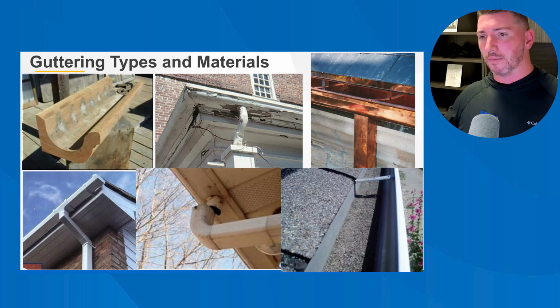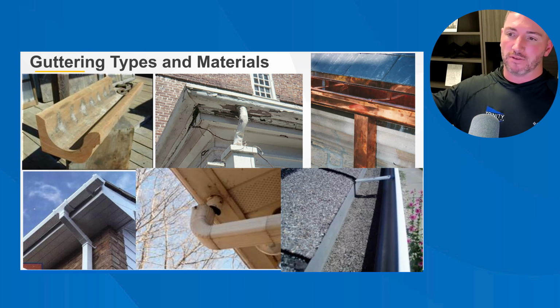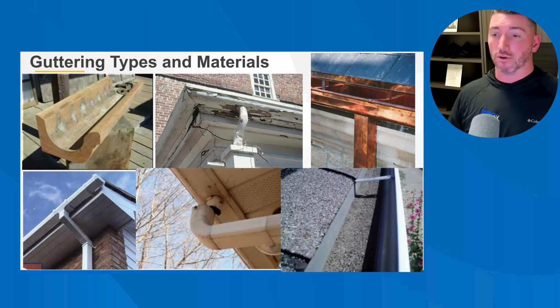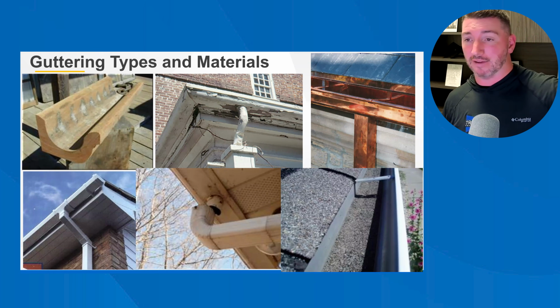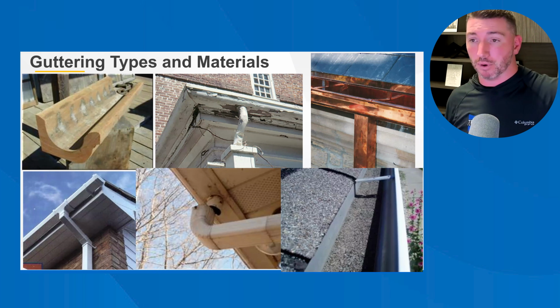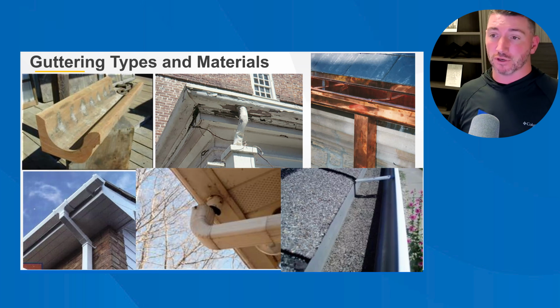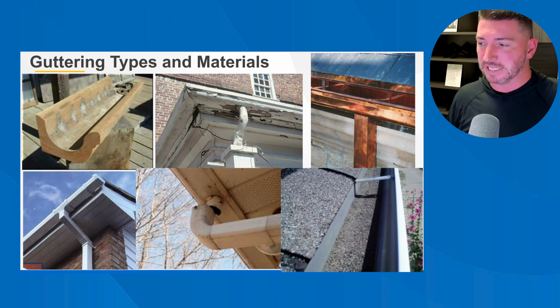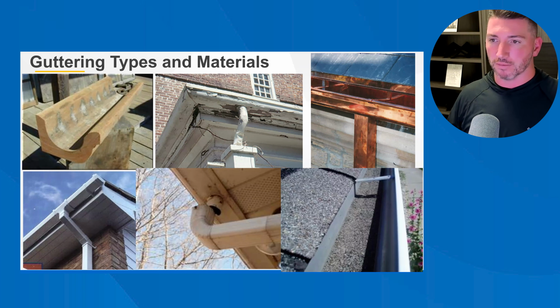But those come in a flat sheet that's in a huge roll, and you mount it on a machine. You feed the end of the roll into the machine, and there is no upper end, no limit on what the run of gutter can be. I've seen a 120-foot run of seamless gutter. Now it's a booger to install, I imagine, but there's no seams in it, and it's much prettier. So a lot of more modern builds are going to have seamless aluminum gutters. That's probably your primary form of guttering in today's day and age.